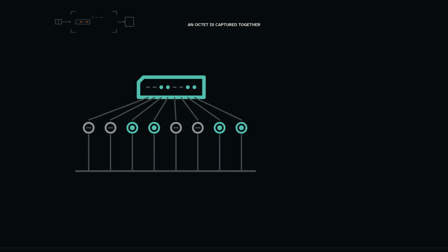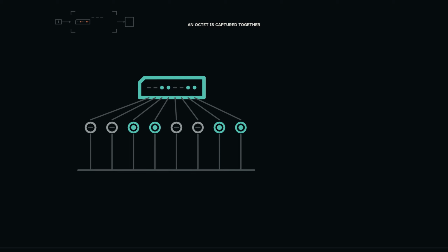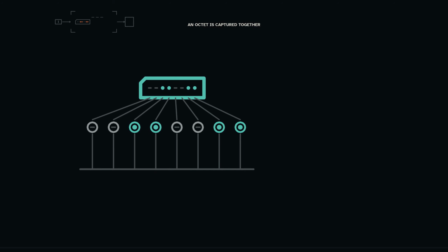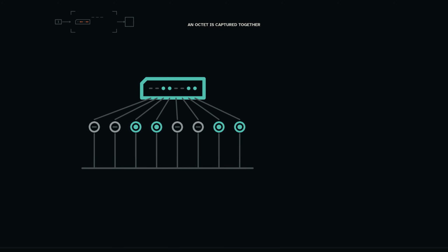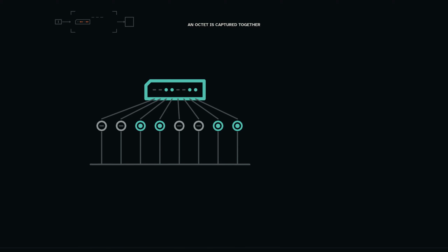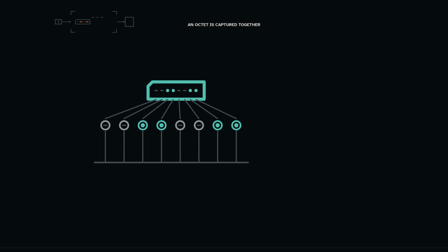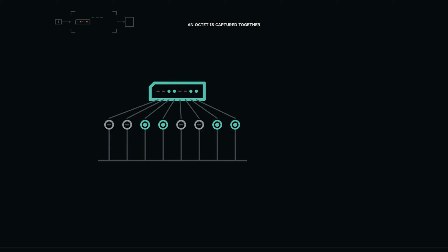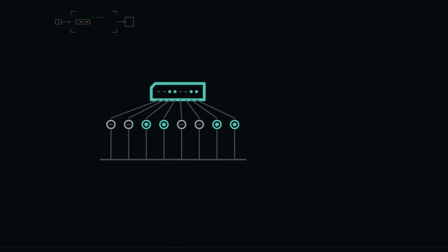Feed the stored 8-bit pattern into an incrementer, a combinational module whose contract is to produce the next pattern in a declared counting sequence. A selector chooses either the unchanged state or the incremented proposal. At each enabled edge, the register captures that proposal. The counter is not a special substance that moves by itself. It is a register, feedback, a next state function, and timed capture.